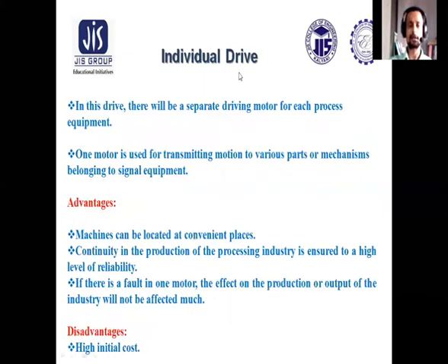Now, what is individual drive? In case of individual drive, a separate driving motor will be used for each process equipment, such as for a lathe machine. What are the advantages? The machine can be located at a convenient place, whenever required. Continuity in the production of the processing industry is ensured with a high level of reliability. In case of fault of one motor, the entire system will not be affected. But it has one disadvantage, that it requires high initial cost.